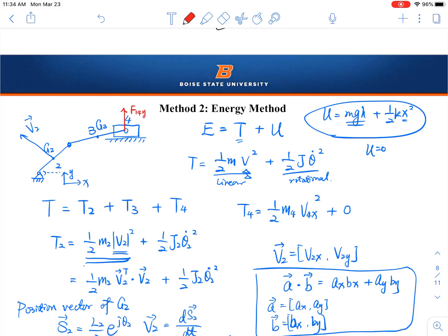We also have the reaction force at the joint, that's F43x and F43y. You also have these reaction forces here, that's F32x, F32y. You have the ground reaction force, F12x, F12y. And you also have a counterclockwise T12 torque generated by the motor fixed to this joint.